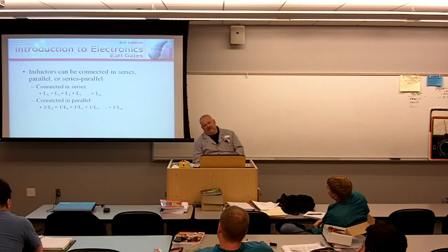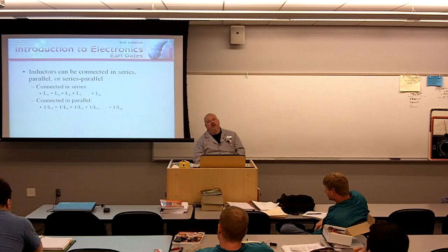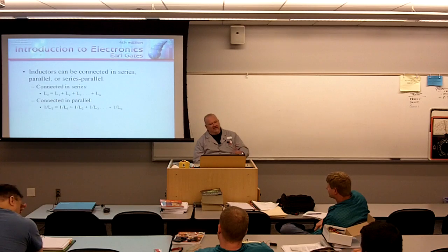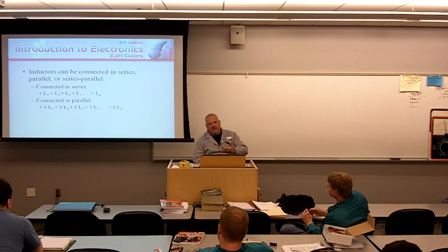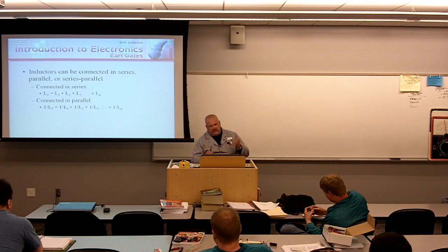Just like resistors, inductors can be connected in series, parallel, or series-parallel. When you're dealing with inductors measured in Henrys, in series, you treat them exactly like resistors, plain and simple. If I've got 2 Henrys and I put it in series with 4 Henrys, 2 plus 4 equals 6.